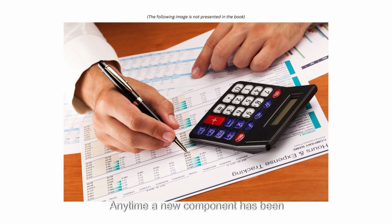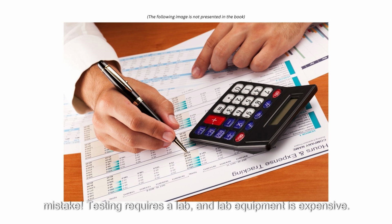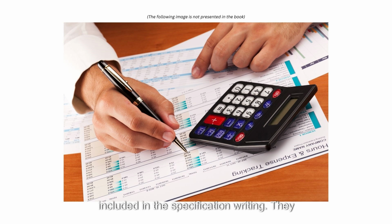Anytime a new component has been introduced to a product that has not been used in the past, there is a learning curve. The datasheets are not always correct, and sometimes the components have flaws in the silicon that do not perform as advertised. And, believe it or not, sometimes the circuit designers even make a mistake. Testing requires a lab, and lab equipment is expensive. This is why the test engineers need to be included in the specification writing. They can tell immediately what testing can be done with equipment in-house, or if they need to procure or make test equipment.